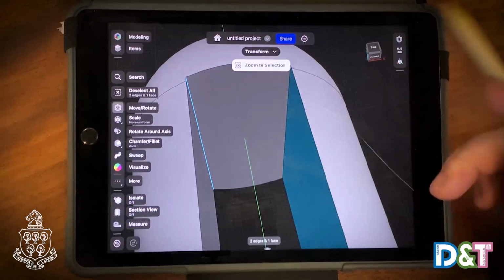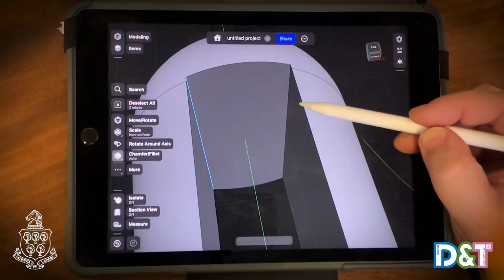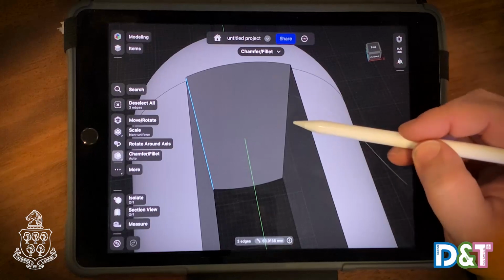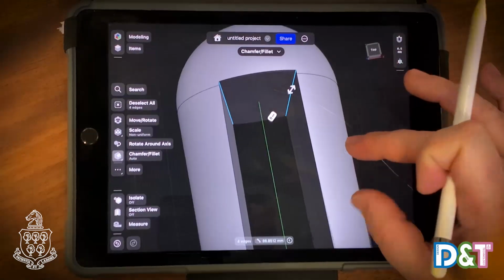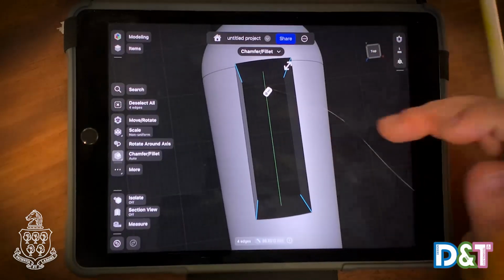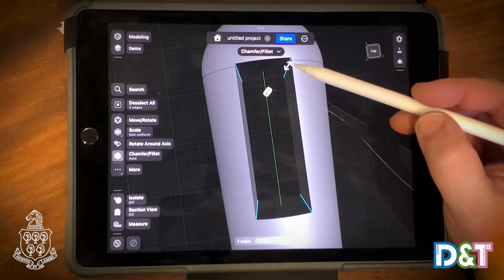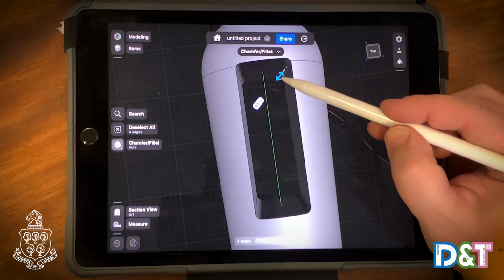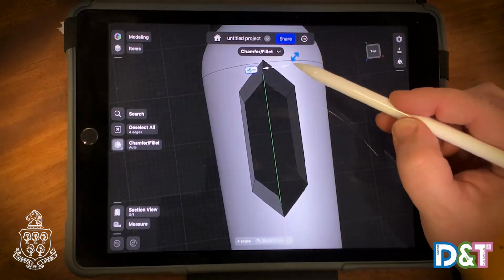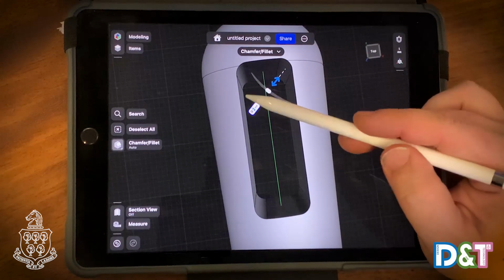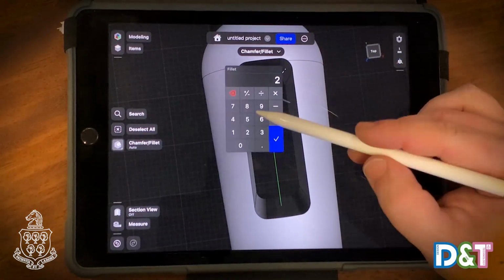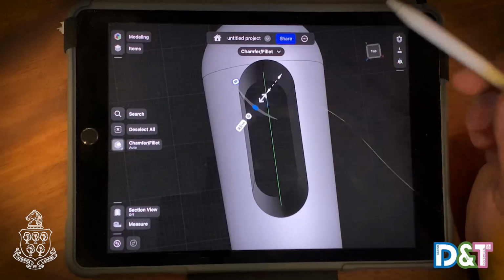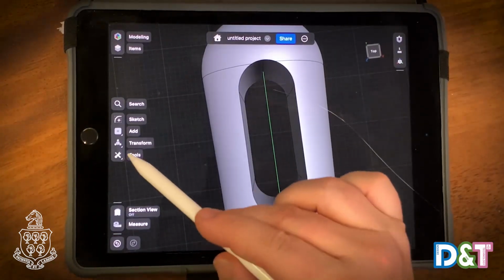Take your time. See, I've actually selected something wrong there. I selected a whole surface, so I've clicked it again to deselect. There we go. And now I've got the 4 corners selected. And the same double-ended arrows turned up, where we can basically do a radius or do a nice chamfer. So I know we need a nice radius of, let me just have a look at it, 5 millimeters in total. So I'm going to hit 5, hit OK, and hit deselect.